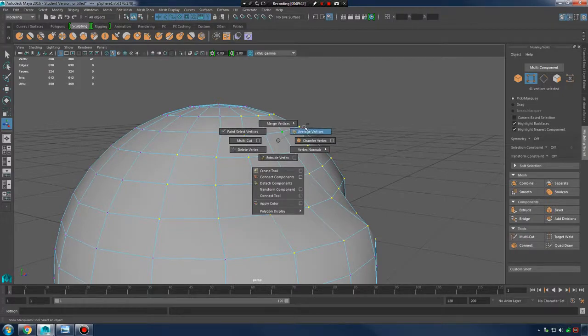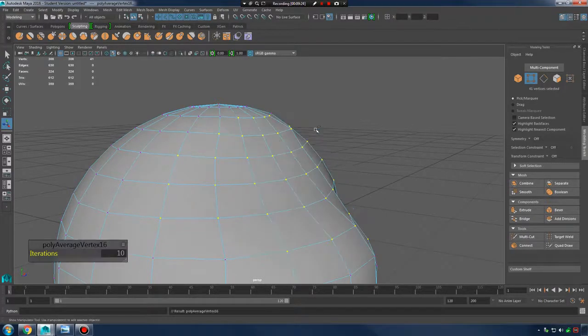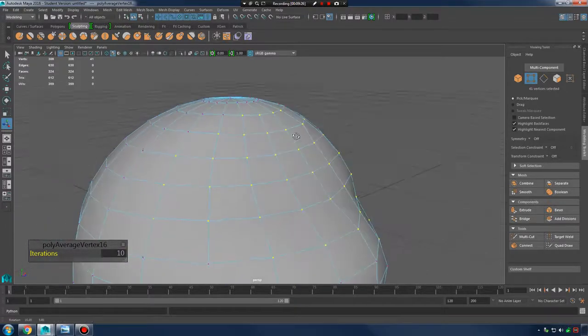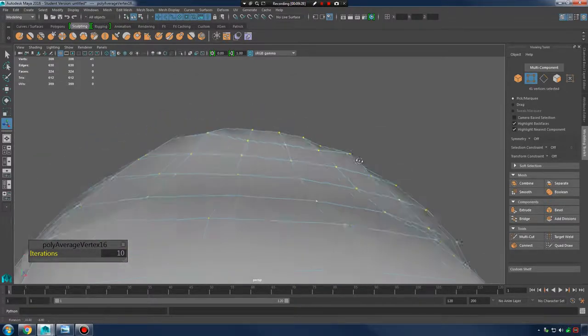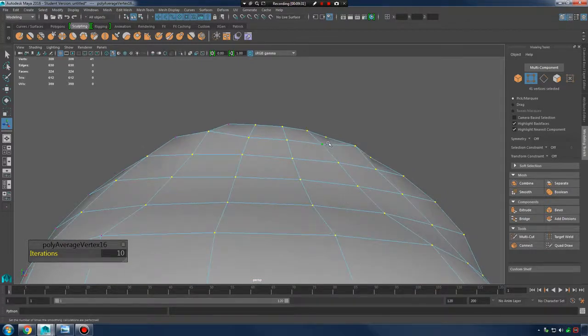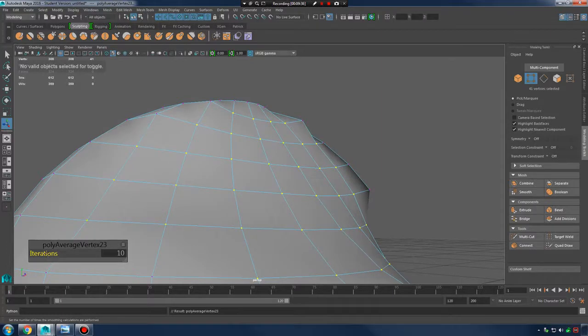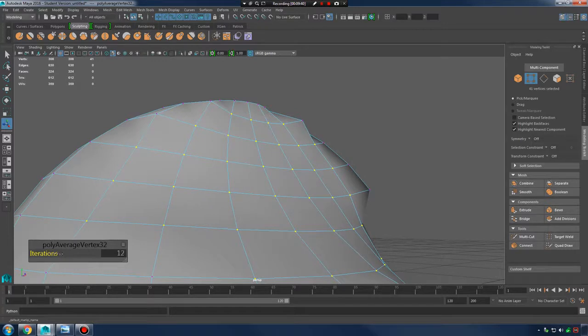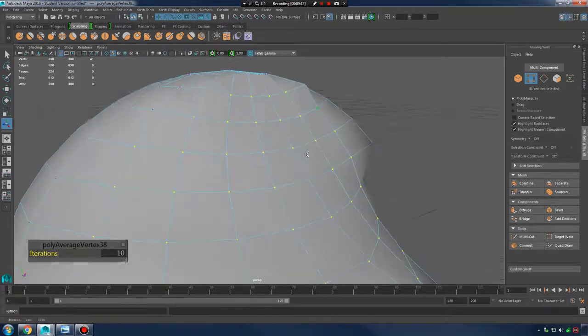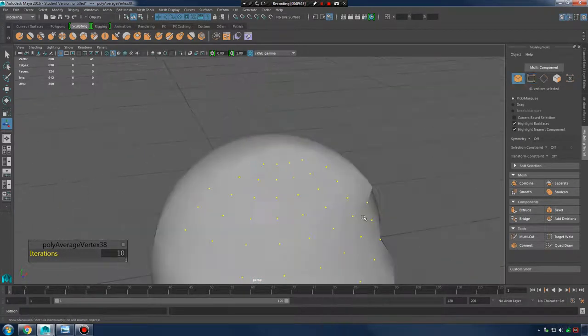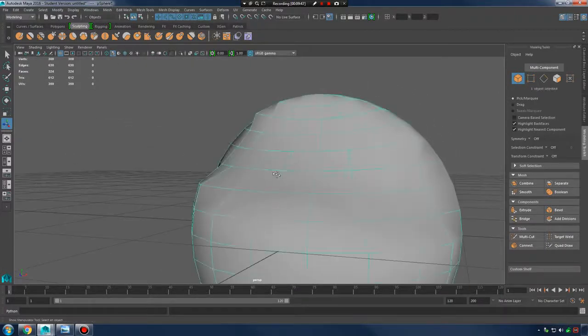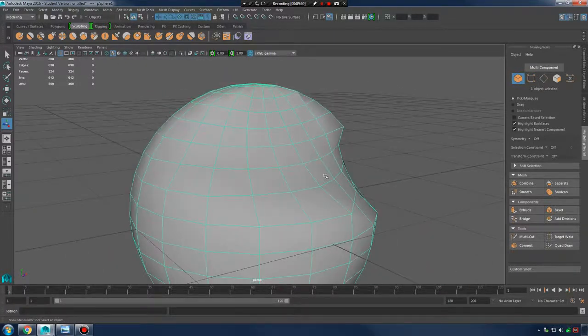So there's also an average vertices shortcut there. Now we're selecting even more of those weird pieces of geometry, creating that jerky non-planar topology. And we're hitting G. And I'm imagining the iterations is basically the severity of your average. So average vertices is nice because we can select just the parts of the model that we want to put a smooth on to create this nice even topology.